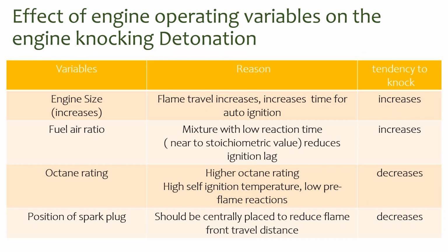When the engine size increases, the flame travel increases and it increases the time for auto-ignition, so the tendency to knock will increase. With the fuel-air ratio, when we use a rich mixture, the tendency to knock will be more. When the octane rating is more, we know that the tendency to knock will be less.